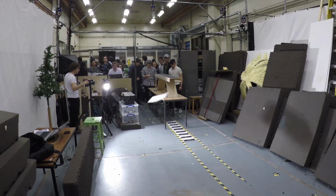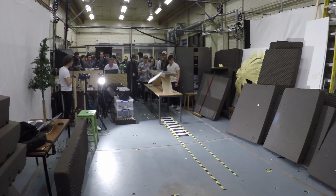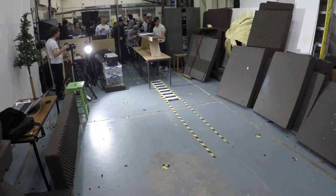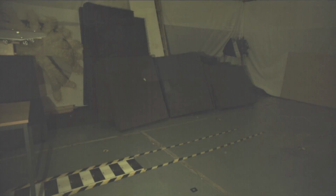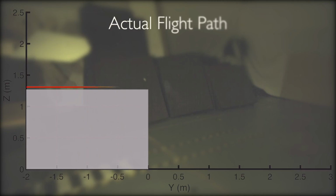On the testing day, not everything went as planned. Even though the glider was driving in a straight line when pushed by hand, it became clear that the torque generated by the motor led to a turning during the acceleration phase, thus leading the glider to exit the ramp on the side and not using the full length of the ramp to reach its maximum speed. As this did not occur during the first tests, we were able to pin the source of this behavior down to the struts, which became loose and had too much clearance.